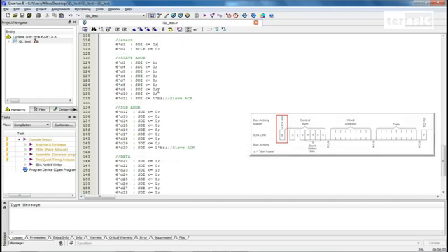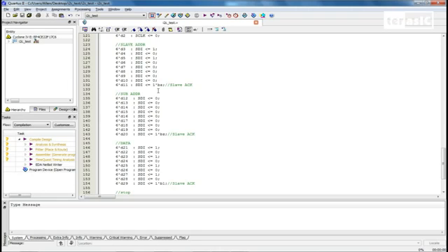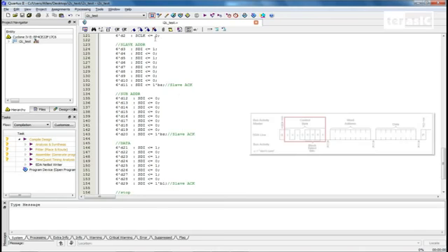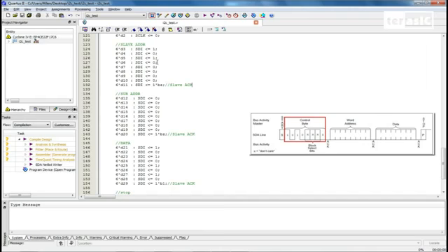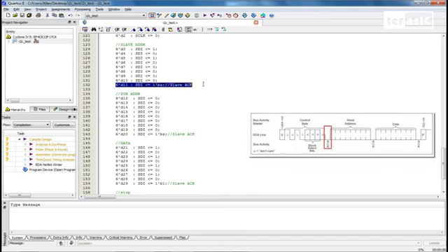And then we can input a regular clock into our EEPROM S-clock, and our SDI, depending on the different counter conditions, will have different values. So first is our slave address. First we'll input our A0, which is 10100000. And then after that, in order to get an acknowledge from the slave, we'll set our bus to tri-state. So the master will basically let go of the bus line for the slave to give an acknowledge. And if the slave pulls the line low, then we know that the slave has acknowledged.